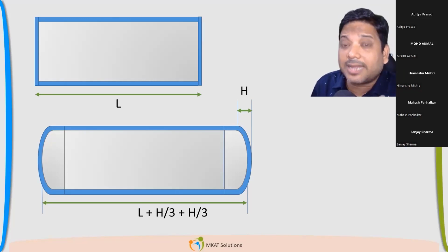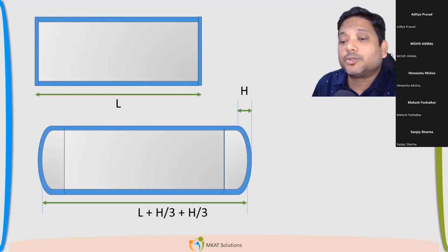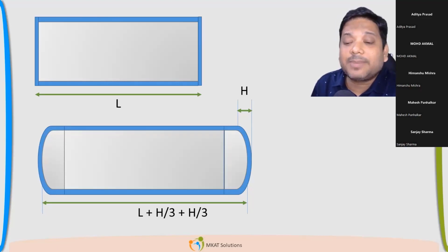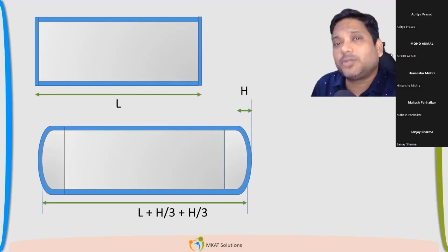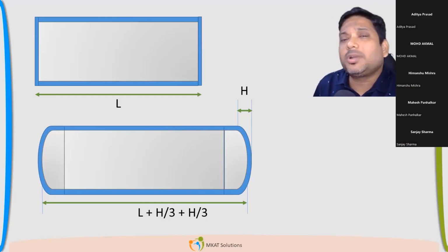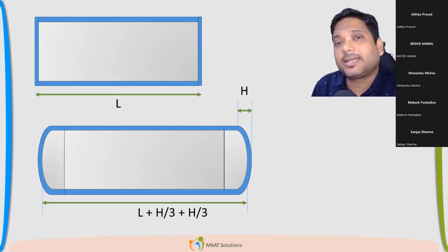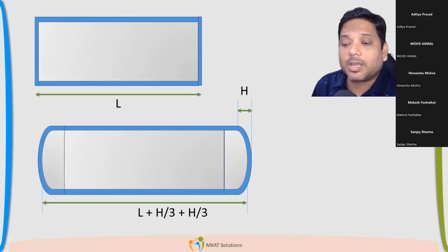You don't have to consider that in H. Okay. So from the tan line to the end, okay, end of the vessel. So that is your H depth. Okay. This H divided by 3. Okay. So that is where approximately your CG will lie. So code is saying approximately where your CG will lie. That point you can take as line of support. So the CG lies at H by 3 points.